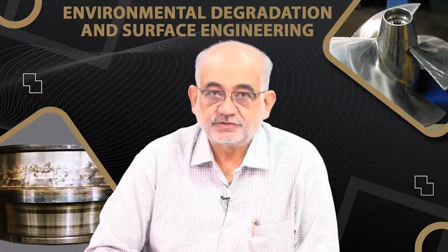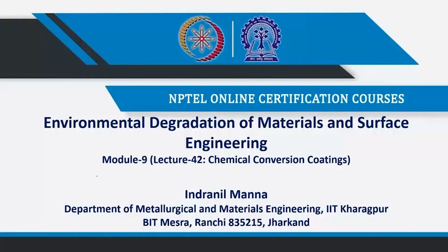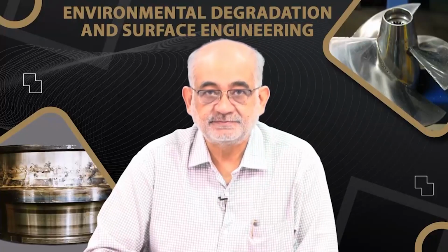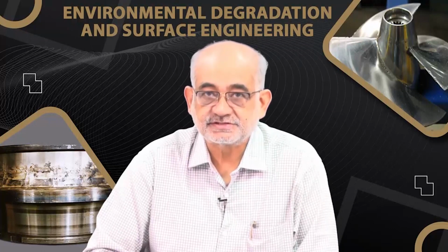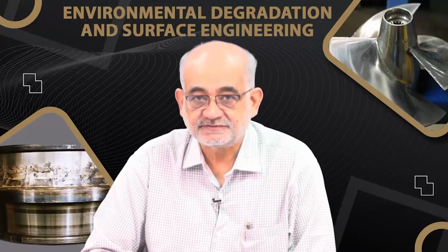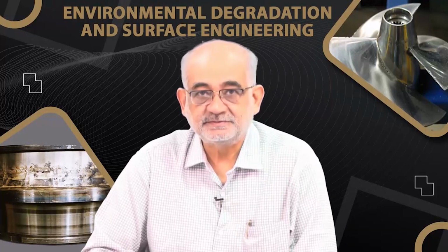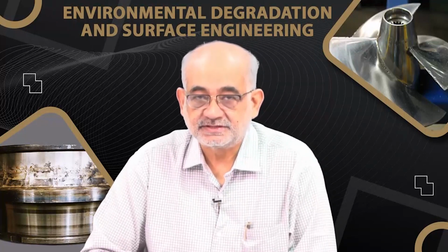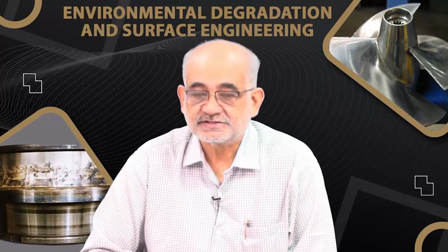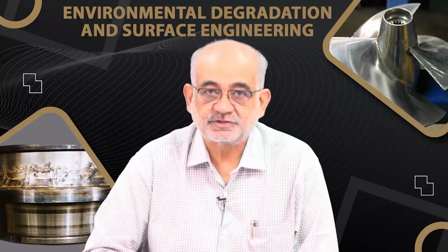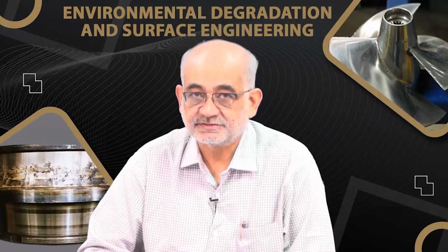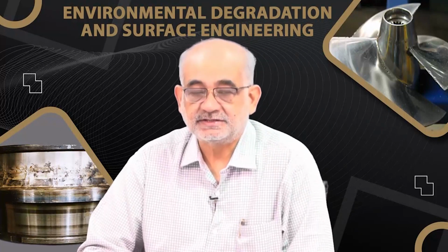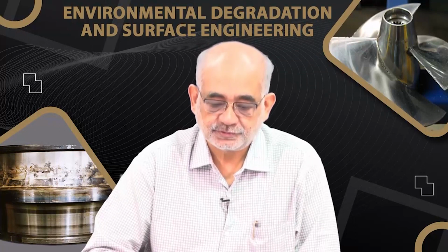Welcome to the lecture 42 of module 9, which is on chemical conversion coatings. In the earlier lecture, we just heard about diffusional processes, so various forms of coatings created by high temperature diffusional processes, whereby we enrich the surface with some specific elements like aluminum, silicon or chromium, which when exposed to high temperature allowed surface protection by way of formation of these respective oxides of alumina, silicon dioxide or chromium oxide.